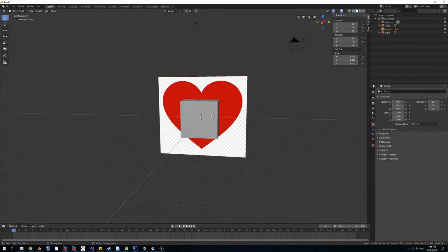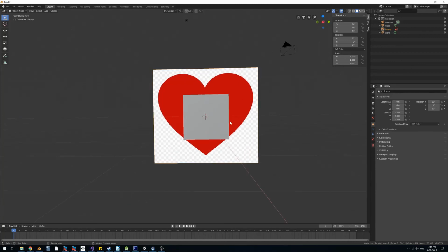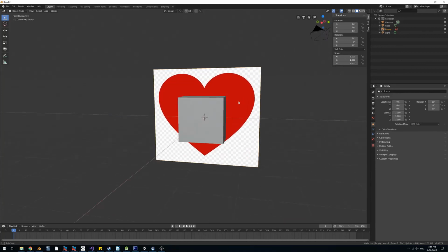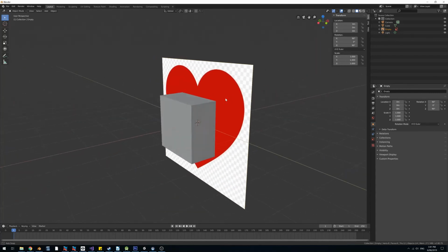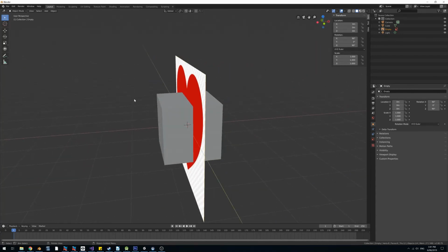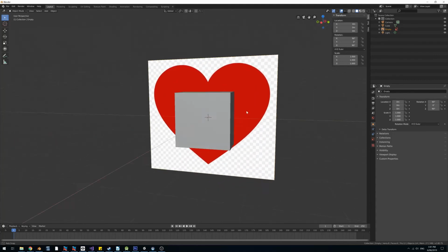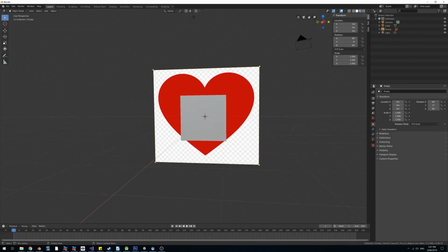So the next thing we want to do is align our camera views so that we have what is called an orthographic view. So in a typical viewport, you'll actually have perspective. And so if you watch these lines, for example, they disappear off to a point in the distance. That actually isn't that useful for us when we're modeling. What we want is all of these lines to become parallel.